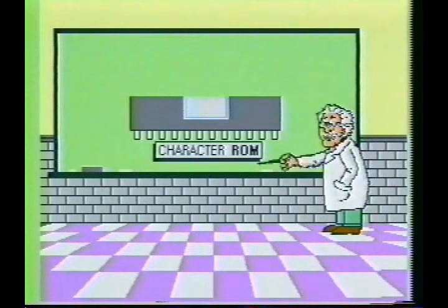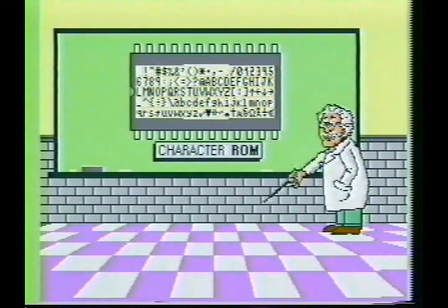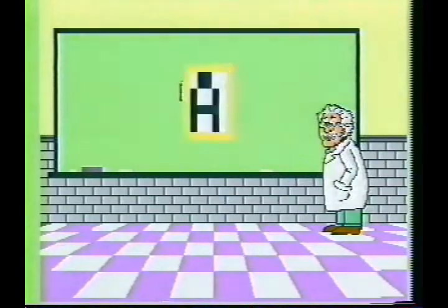The character generator, or character ROM, is programmed with the patterns of characters which get displayed on the screen. This is referred to as the character font. The character font for every letter is made up of a block of bits. The bit's logic state determines if a point of light will be scanned onto the face of the monitor. A point of light is also referred to as a dot or pixel.